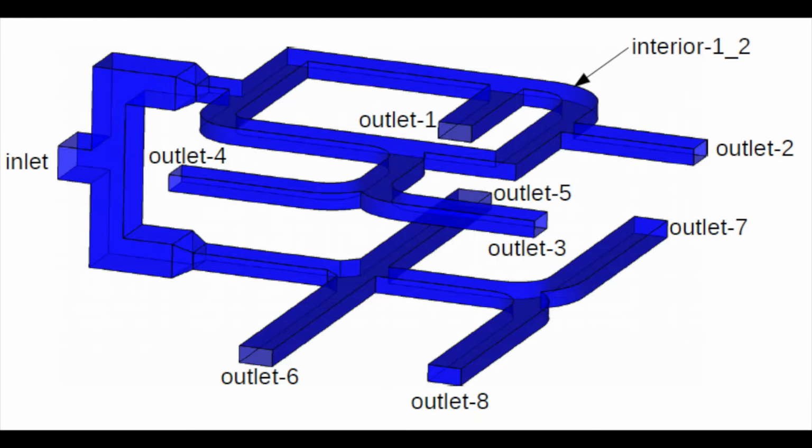Flow for the HVAC system enters through a single model inlet shown at left. The flow then splits to two branches, one on the first floor and one on the second floor of the building. There are 4 outlet vents per floor, and the ductwork features a variety of geometry elements, including contractions, curved elbows, square elbows, T-junctions, and Y-junctions.